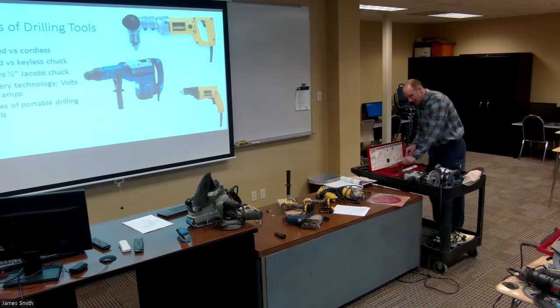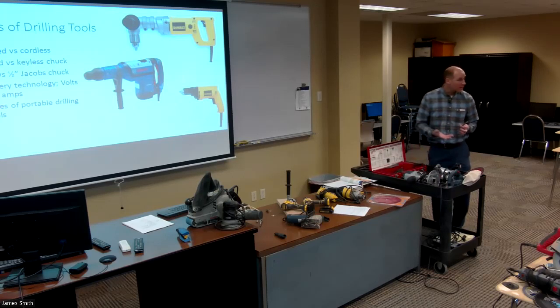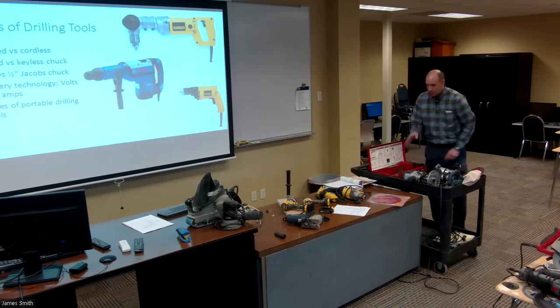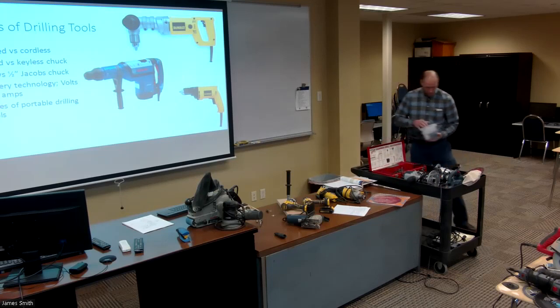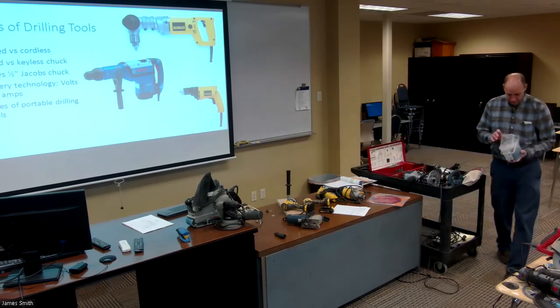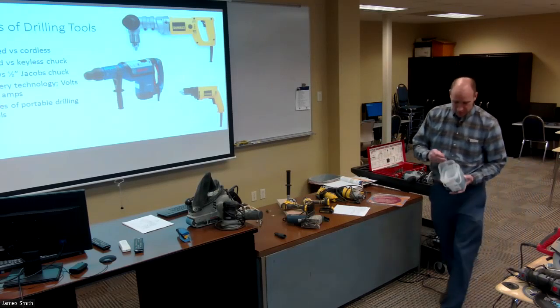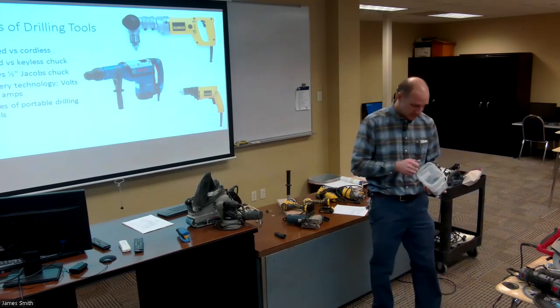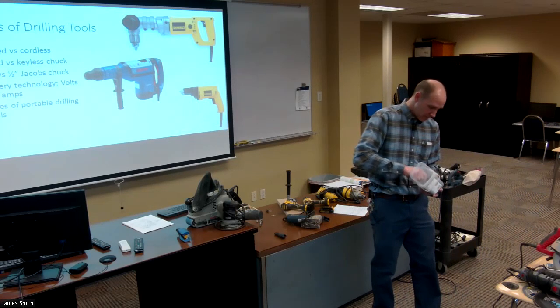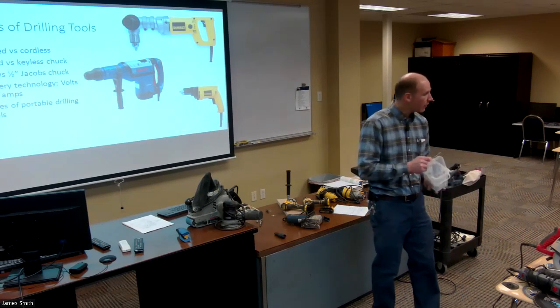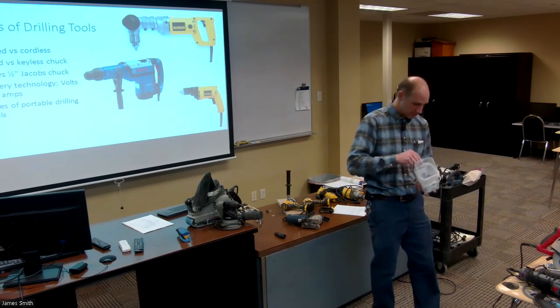If you've got real big bits and you need a lot of torque to turn those, and they're real deep holes, you're going to want to use something big like that. But for little drilling jobs, like setting little Tapcon screws like this, and you're running these little bits, those little battery powered drills are more than sufficient. Okay.